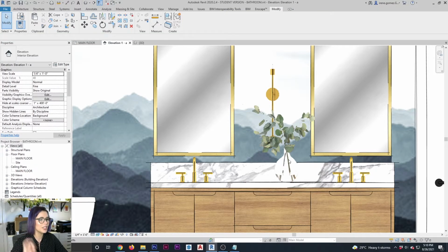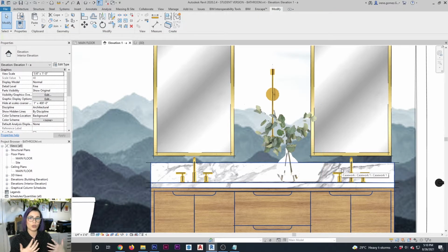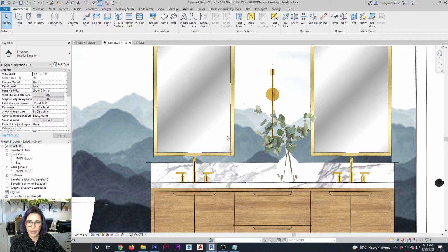Now, here's the other important thing when you're gonna pull out this trick. Who is in front of who is very important. So for example, when you work with annotation details in Revit, you are given this option where you can choose who's in the front, who's in the back. When you're actually modeling geometry, you don't really get that option. So the thickness or the depth of your object will determine who is in front of whom.